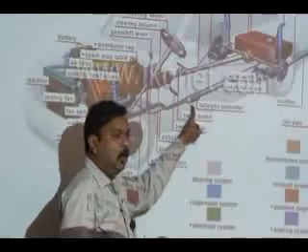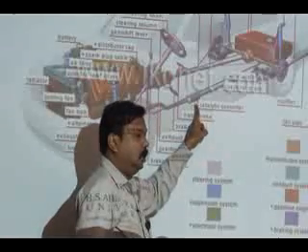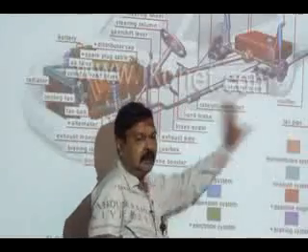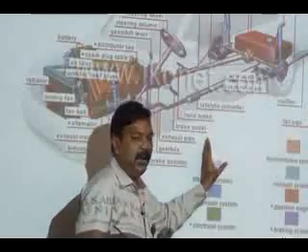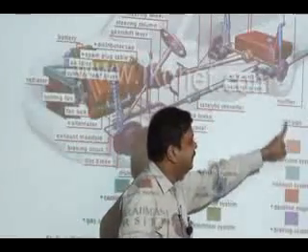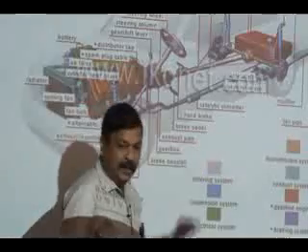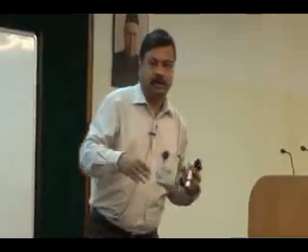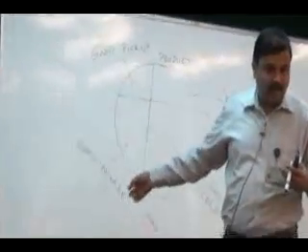We have some noble metals here which are catalysts, which will promote complete oxidation and minimize the pollutants. Then you have the silencer or muffler. A muffler is essentially a sound arrestor, a silencer. It controls the velocity, and then you have a tailpipe through which the gas goes.